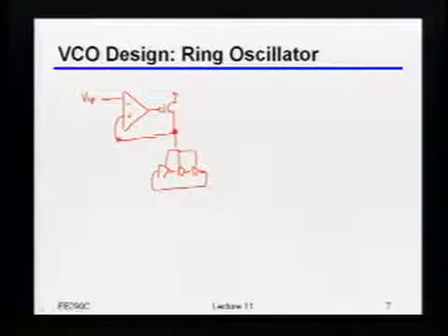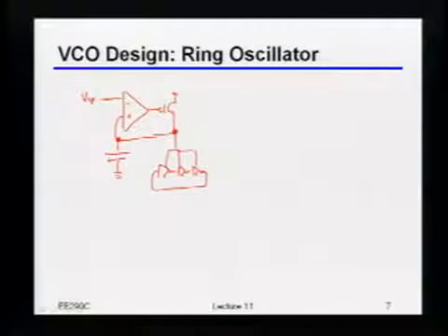Okay, a few things to note and a few questions that I'll ask you. First of all, if you do something like this, you're generally going to want to put a pretty big cap right there. Remember, you might be on some processor or FPGA, and that's going to have 10 billion digital gates jumping around and creating all kinds of glitches on the supply. So you really want that control voltage to be as stable as you can make it. We'll talk a whole lot more about some issues with how you build these regulators, but for now, take it for granted that there should definitely be a big decap at the output there.